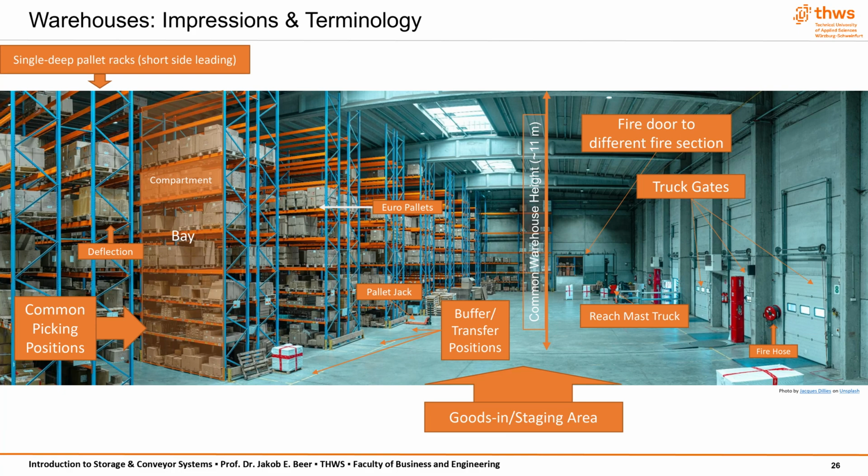This risk becomes especially critical in high bay warehouses, where items may fall from heights of 12 to 18 meters. Even without a complete collapse, a pallet that deforms too much may no longer function properly in automated environments. Many conveyor systems and automated storage and retrieval systems rely on strict dimensional accuracy. A sagging pallet can jam, misalign, or be rejected by the system entirely. In addition to that, excessive deflection can compromise vertical clearance between racking levels, which is particularly problematic in dense storage environments with little room for error.